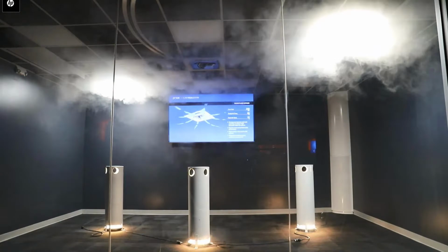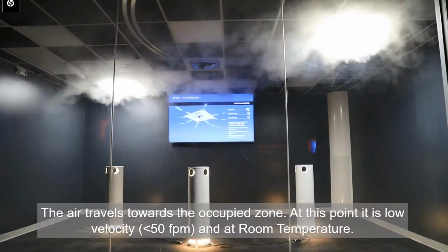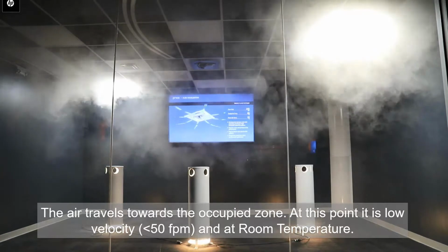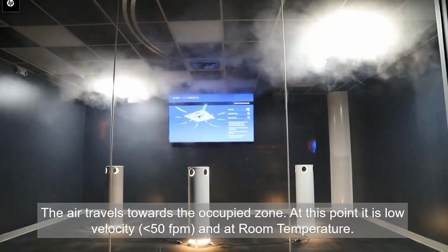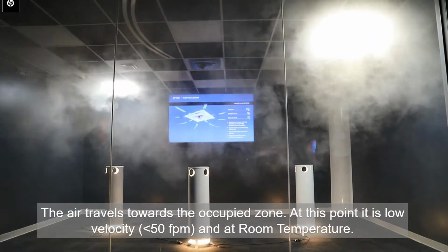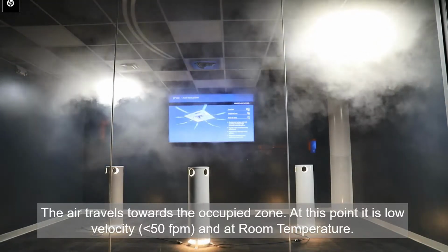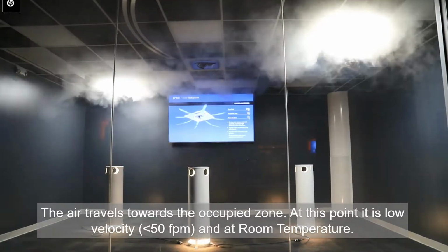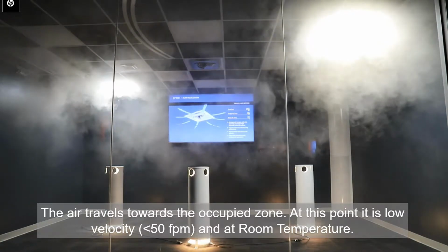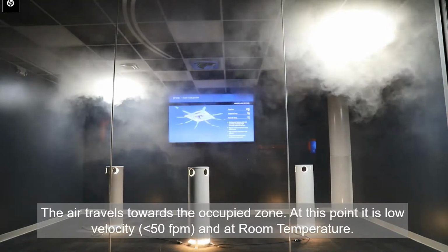As the air travels across the ceiling, it will eventually come to a wall or some boundary. We'd like to place our diffuser such that by the time the air enters what we call the occupied zone, or roughly 6 feet above the floor, it is slowed down enough to reach about 50 feet per minute. 50 feet per minute is a rule of thumb velocity that we use, because once you're below 50 feet per minute, the air is slow enough that you typically won't have a draft, and it is also warmed up to room temperature at that point. This way we're mixing air throughout the space, but it's not creating a draft, and it's not noticeable to the occupants.